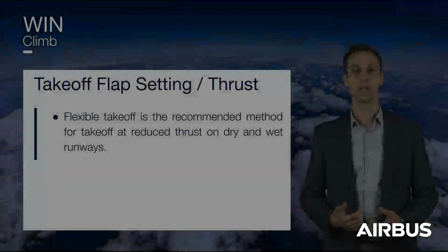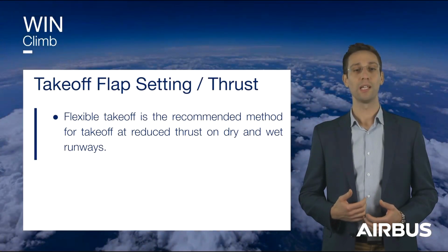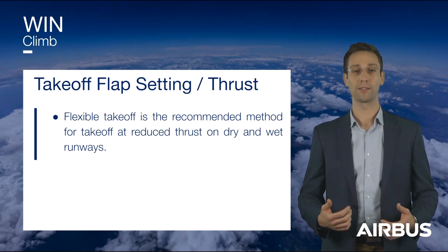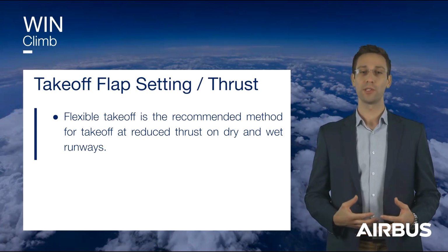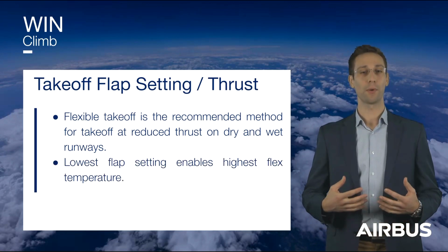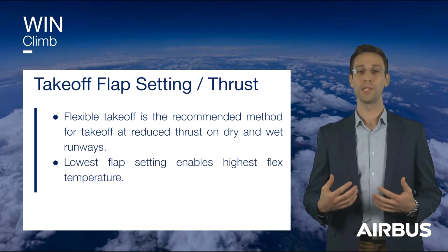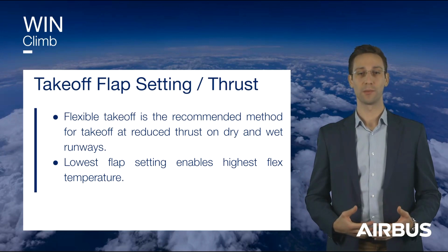The advantage of operating the engines at a lower thrust compared with full power is an extension in engine life and reduced maintenance costs. The flexible takeoff is the recommended method for takeoff at reduced thrust on dry and wet runways. It must be noted that the highest flex temperature will usually be obtained at the lowest flap setting.